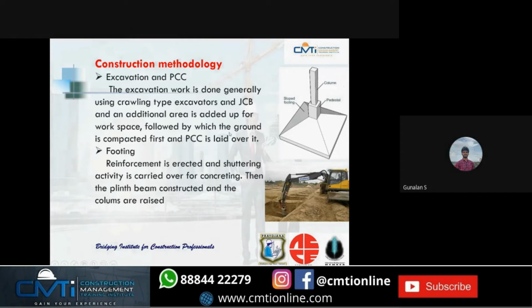Next is PCC. Before laying of PCC, the ground should be compacted. Next, footing. The reinforcement is erected and shuttering activity is carried over for the concreting. Then the plinth beam is constructed and the columns are raised.